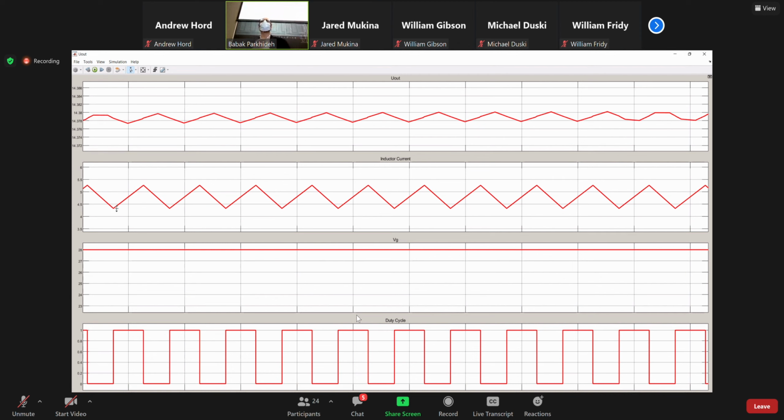So you have about 1 ampere peak to peak. And the average maybe is like 4.7 or something. Okay. So when we have a non-zero bias or average going to the inductor, we call this a continuous conduction mode. And that's what we use extensively in our previous lectures.